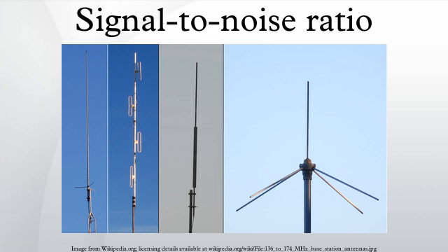The quantization noise approximates a sawtooth wave with peak-to-peak amplitude of 1 quantization level and uniform distribution. In this case, the SNR is approximately... Floating point. Floating point numbers provide a way to trade off signal-to-noise ratio for an increase in dynamic range. For n-bit floating point numbers, with n bits in the mantissa and m bits in the exponent... Note that the dynamic range is much larger than fixed point, but at a cost of a worse signal-to-noise ratio.